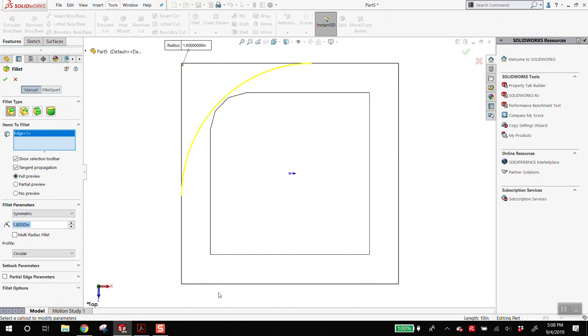A design feature is something that exists from the beginning, something that you want to be what it is. It's part of your design intent. A fillet is kind of like a finish to it. You're just adding around to the edge. So putting a fillet high up in your tree as a design feature is not a good idea.